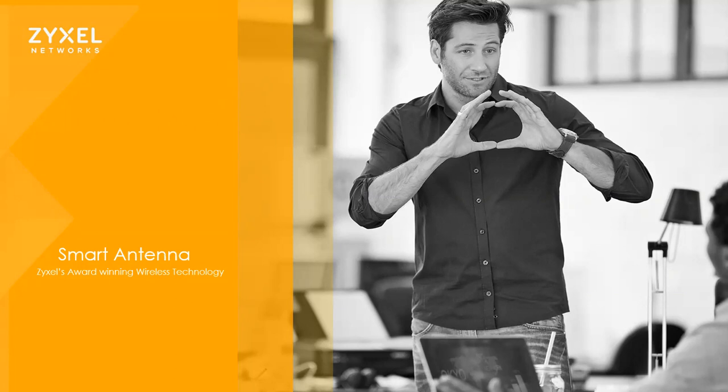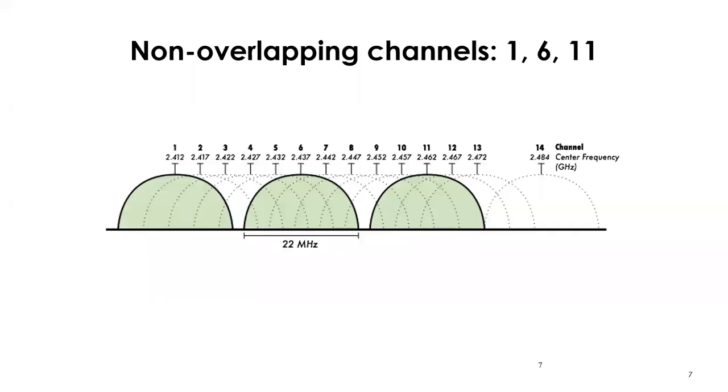We're going to back up a little bit here and talk about how RF works. I go into much more depth on this in our Wi-Fi 101 webinars. But the short version is, when it comes to Wi-Fi, you're using radio frequencies. And for the most part, only one device can transmit at a time on the same frequency. If two or more devices transmit at the same time, you get interference, packets get dropped, and things have to be rebroadcast.